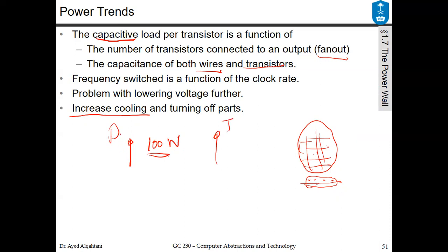If there is too much power consumption, the temperature is going to be high. This temperature affects the IC. Sometimes it reduces its performance, and sometimes it causes damage or certain errors that cannot be recovered. So to manage this temperature, now, we didn't fix the power problem. We managed only the after effect, which is the temperature, and we reduce it by cooling methods. Some cooling methods use fans, or sometimes liquids.